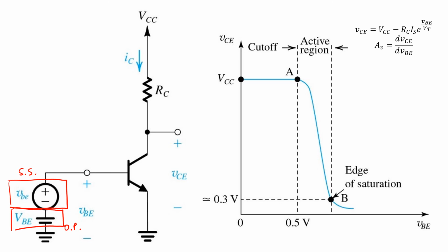And we may be interested in relating the small signal input vbe to the small signal output, which is superimposed on the DC operating point at the output. Again, if we want to use this circuit as an amplifier, we likely want to bias it at the operating point Q somewhere in the region where the transistor is in active mode. And if we do so, the input-output relationship is governed by this exponential equation up here.